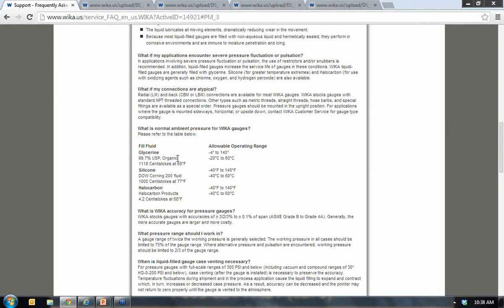The problem with the pigtail siphon is that, number one, it's a very tall assembly, and when it's installed around vibrating equipment, it will induce gauge whip on the gauge and lead to accelerated failure that way. Number two, and I discussed this in the presentation, far too often these pigtail siphons get wrapped in insulation, and that completely negates the cooling effects of the siphon, which is why it's been installed there.